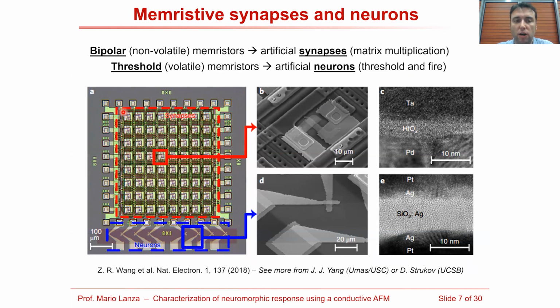Each perceptron is one column and it contains 8 inputs. The input value is multiplied by the conductance of this synaptic memristor. Then all the values here are summed and transmitted to this neuron, which is what makes the comparison.